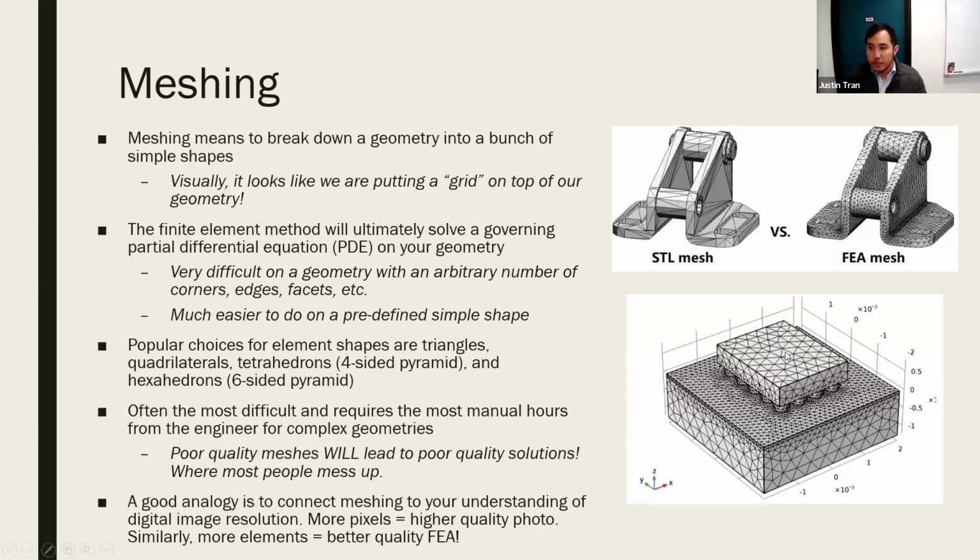And so, for example, for this geometry here, you can see that we've broken the surface up into all triangles. Okay. And then on the interior, those triangles actually turn into tetrahedrons. Okay. So this is actually really important, and you need to do this in order to solve the equation. Okay.